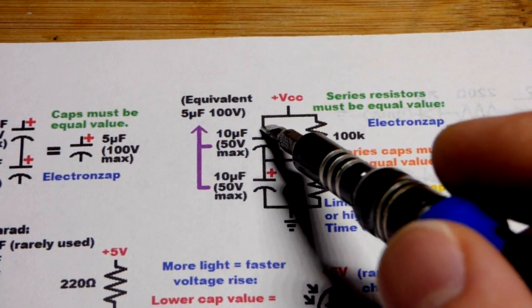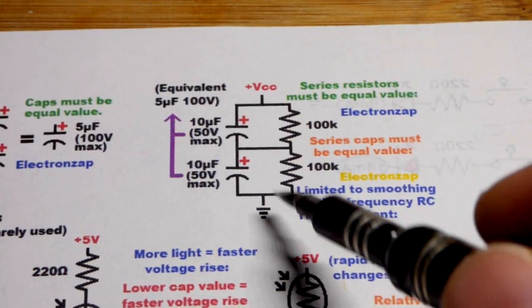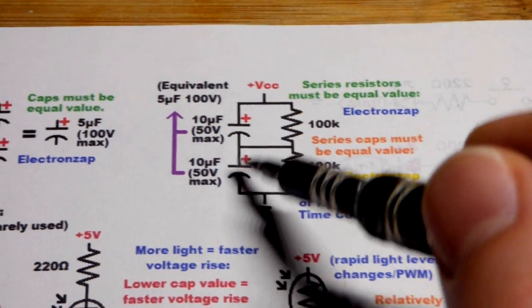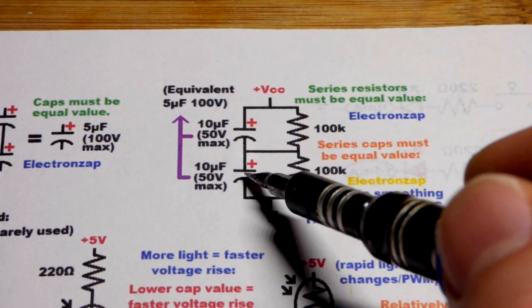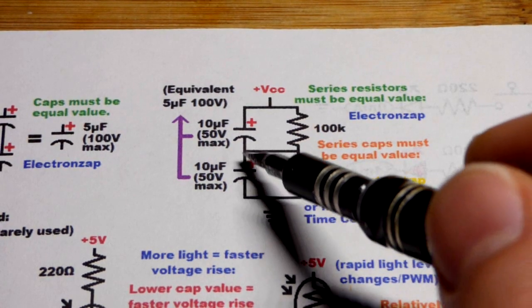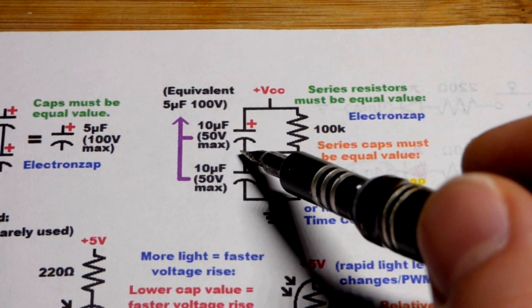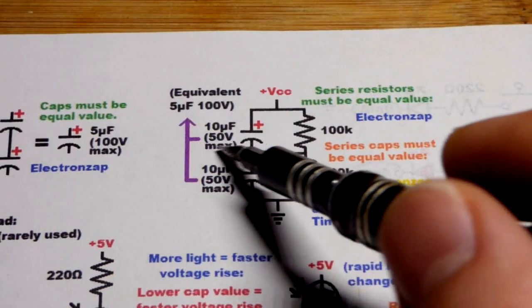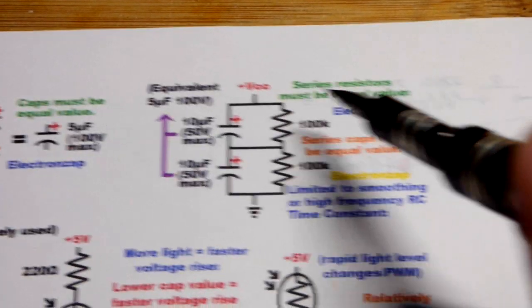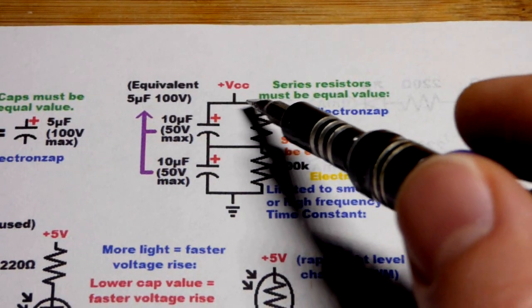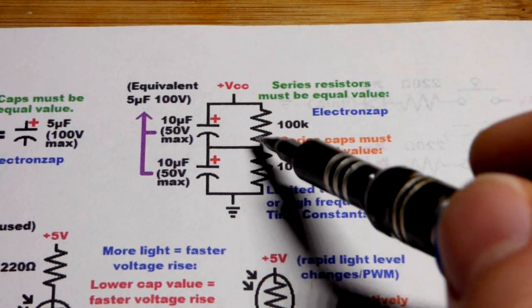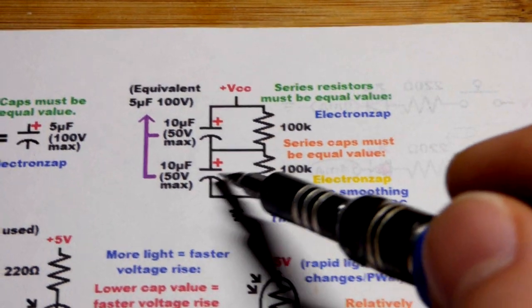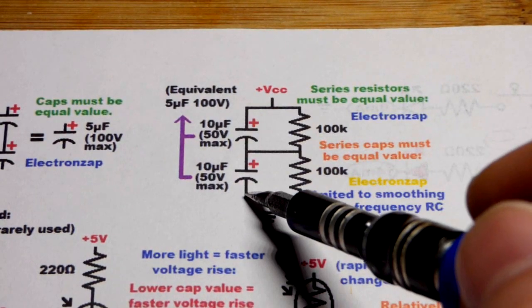But their voltages add up, so you can get a higher voltage than either one alone. Problem is, one of them may charge quicker than the other for whatever reason. The other one might have a little leakage or something. It discharges a little bit. They can become unbalanced, and so you might get more than 50 volts on one of them, even with 100 volts. So the voltage divider can come in here. It divides up the voltage from the supply, helping to keep them equalized right there.